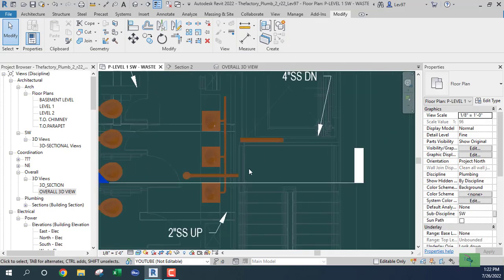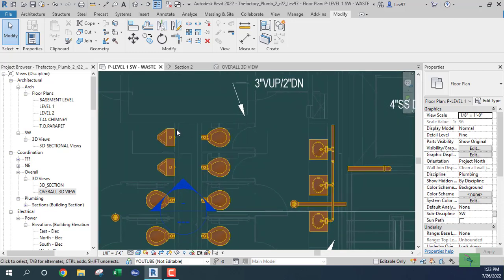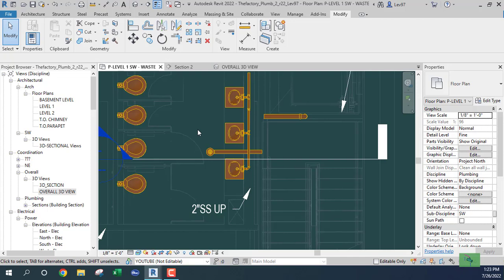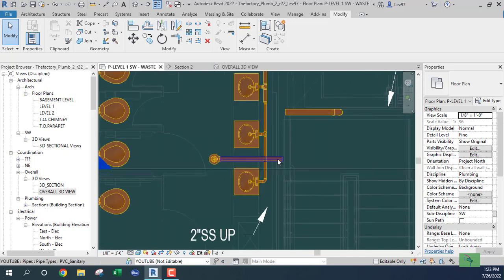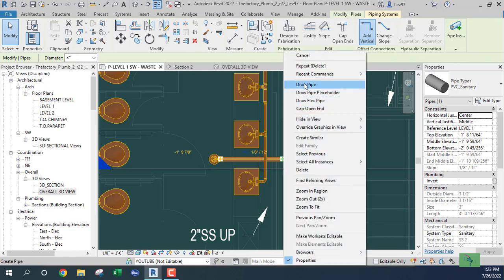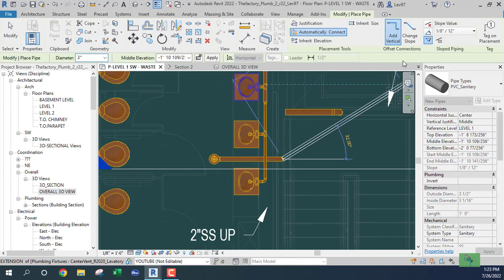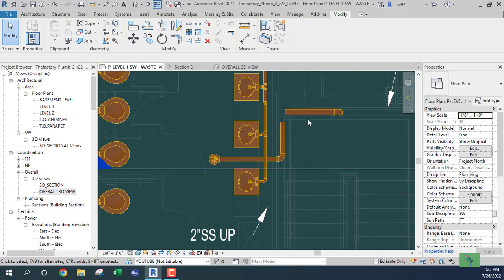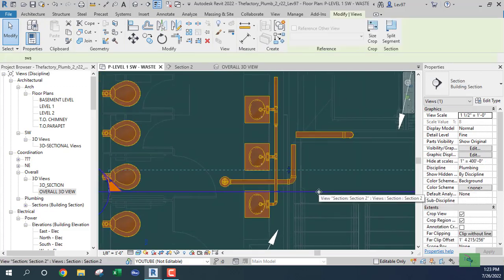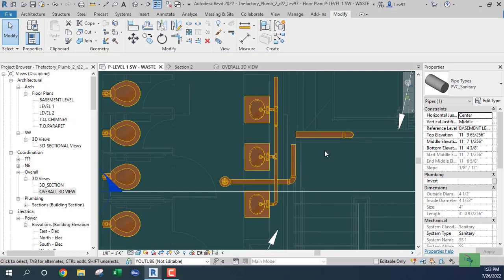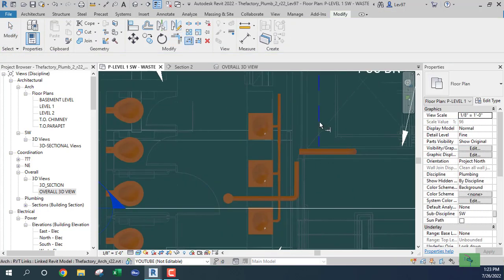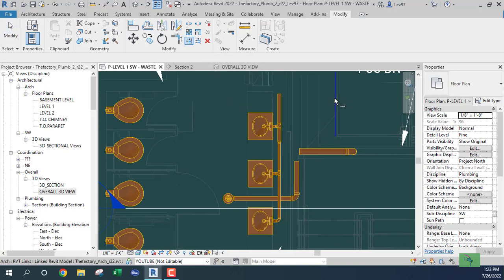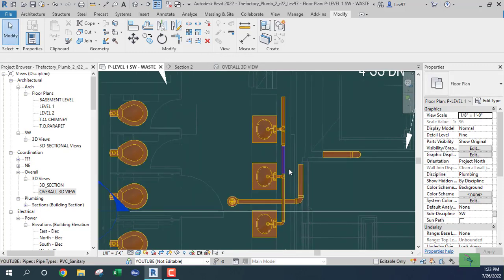I need to connect this pipe, the one from the sump, and these from the 3 lavatories, and then go over to connect to this piping that's going to be done later. But I need to draw this pipe and down. Let's see where it should be. Let's trim that out. You can use any of these lines. See, trim this one, that one, just to get it back.